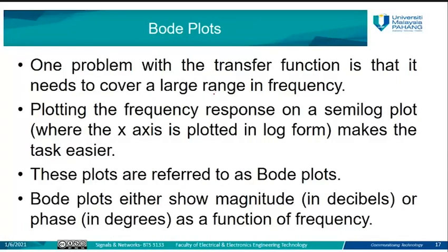So we can say this system is stable, this system is unstable, this system represents a low pass filter, and this system represents a high pass filter. This is the cutoff frequency of this system, that is the cutoff frequency of that system, and so on. It is a graph using semi-log paper, and from this graph we can understand a lot of information about the system behavior or system response in the frequency domain.